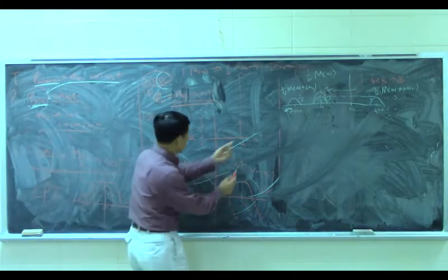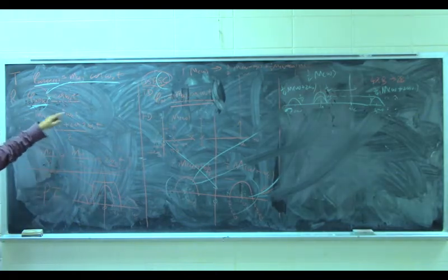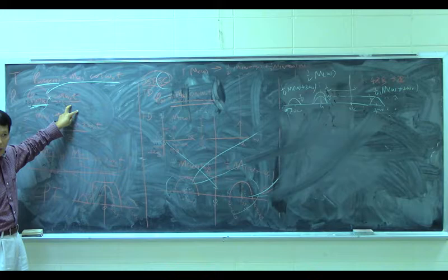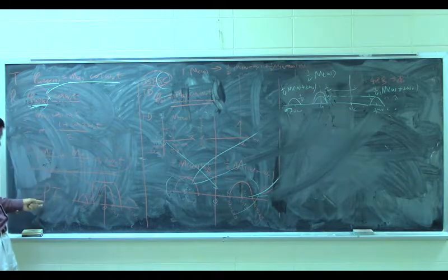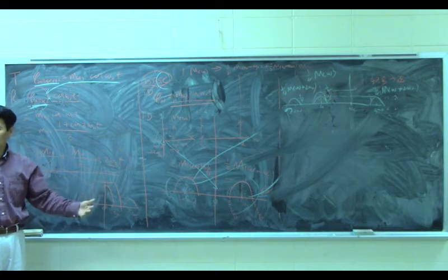This frequency is much higher than this 20K. Okay? So you receive a signal, you multiply by your carrier signal again. Then you pass through a low pass filter, you get what you want. That is how we explain this in time.